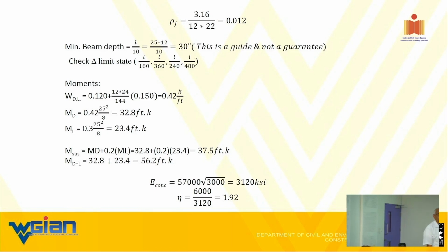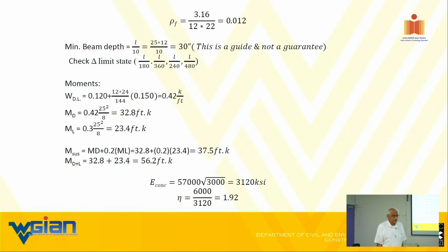Deflection limit state in the US, we primarily state it's a function of human response, meaning as you keep walking, for example, the floors vibrate. You don't want that. You feel odd when that happens.